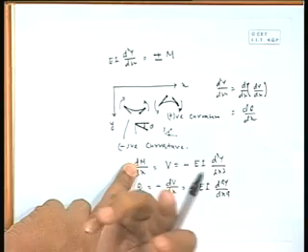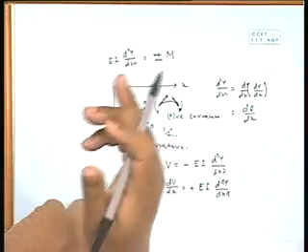So, shear force should be 0, right. Any maximum or minimum quantity will go to a peak and come to the lower side, means their slope, means derivative, will be equal to 0. So, if we equate the shear force equation to 0, you will get the location, the value of x, at what x value shear force is becoming 0, corresponding to that value your bending moment will be maximum. So, that x value you can substitute in the expression of bending moment and get the maximum value of the bending moment there. Okay. So, this information we will sometimes be using for finding out some specific problem.